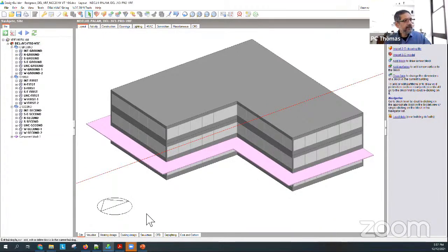Obviously, what you'll do is make some changes and try out how these might be impacted. If you do shading, or improve the window performance, or make the lighting system more efficient, or your equipment loads go down, or the number of people in the space reduces, so the heat from them comes down, then the cooling load will come down, okay?